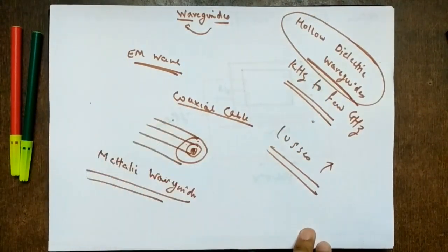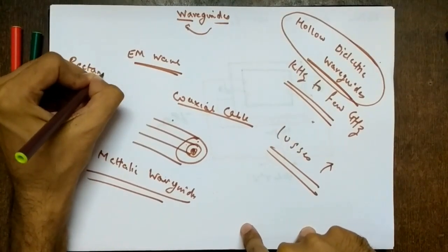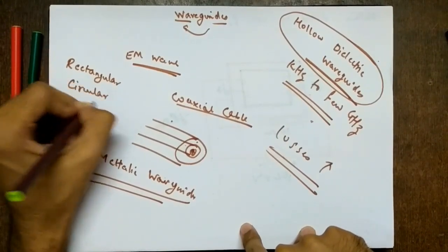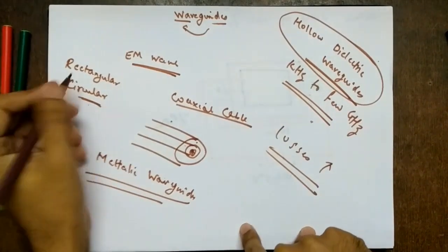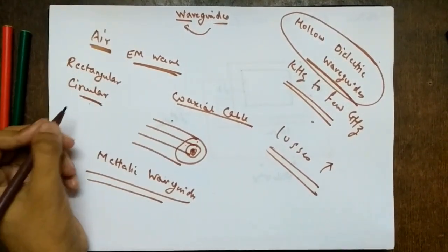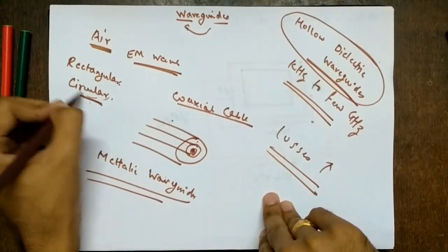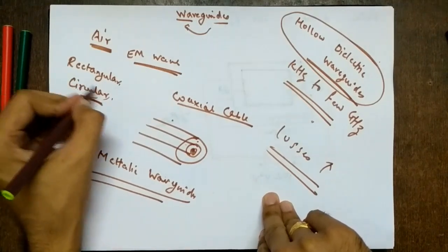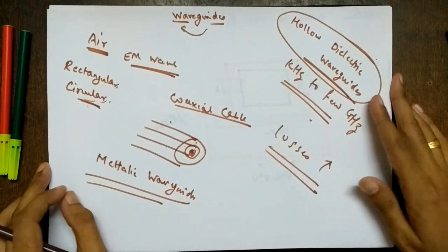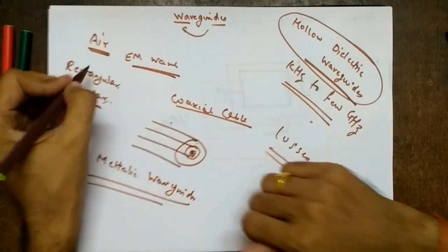Right? So what are those types of waveguides? They are simply rectangular waveguides and circular waveguides. Both are hollow. Right? So they are separated by a dielectric, which is usually air. Okay. So these are the two types of waveguides we study in this module. We will not go for circular because it is very complicated. So we'll just leave that and study rectangular waveguide mainly in this module, and then we'll go to other passive devices which are resonators, isolators, gyrators, circulators. So first thing is about waveguides.